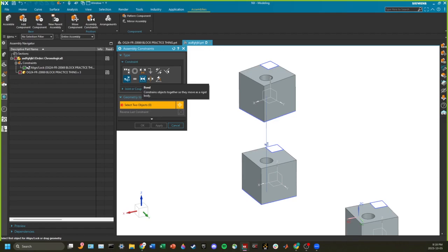We had the chassis jig, and the chassis sat on this big wooden board with these arms poking out that held it in place. In order to put the A-arm nodes on, these little square pieces at really weird angles, we 3D printed a ton of little adapters that would fit onto the end of the wood pieces and then fit inside the metal tube so that it perfectly lined up.